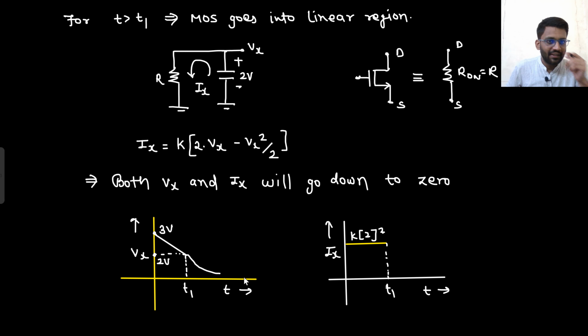If the interviewer asks you how the waveform will go, you will not say, sir, it will certainly go down exponentially. No, no, no. Sir, nearly exponentially. Why is it nearly exponentially? Because when I derived the formula of R1, it has the VDS term. So this R value is not constant. It depends on the VDS value.